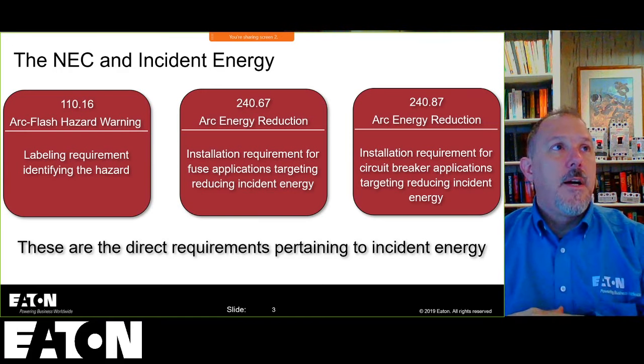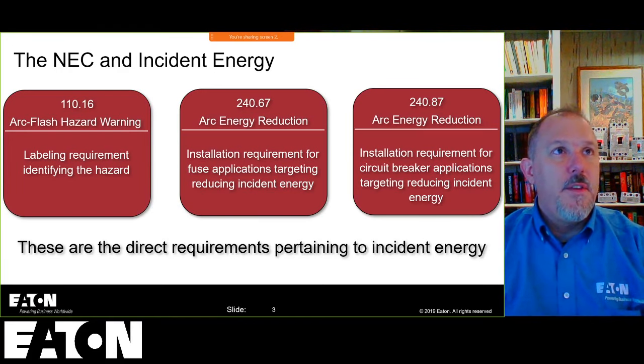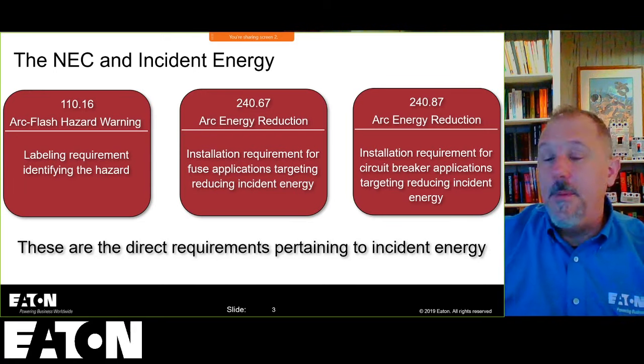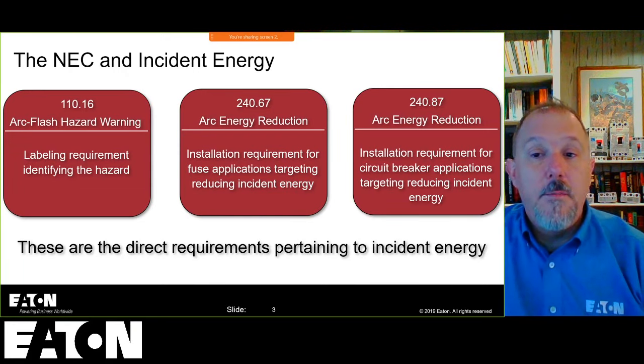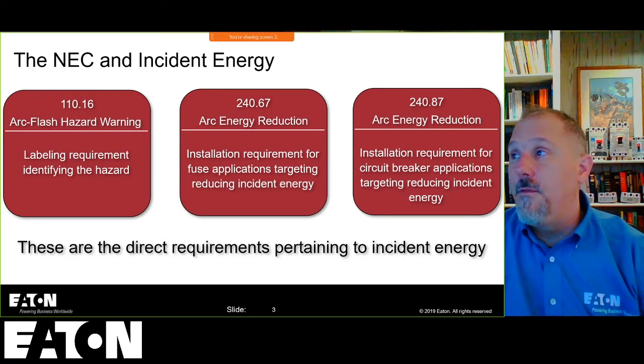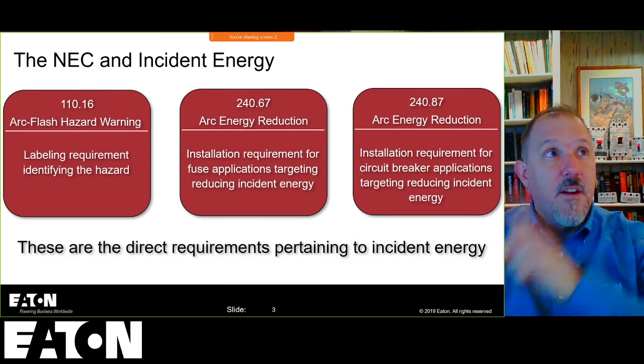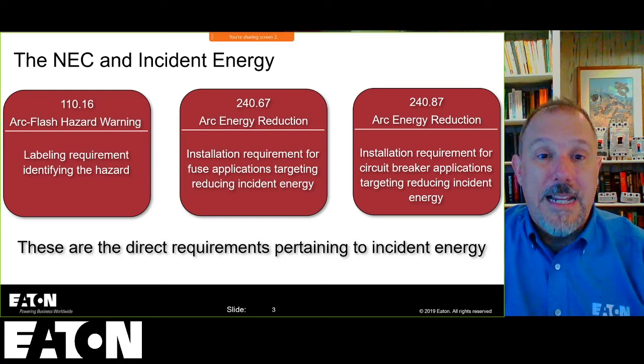And then Vixer, some of our clients would ask us to use 50% of the utility fault current for worst case arc flash if the utility only provides maximum. And I'll tell you what, Vixer, you're going to be happy with the IEEE paper that I give you, because not only is your customer asking you for it, but there was an IEEE paper that verifies that percentage number, and we're going to get to that.